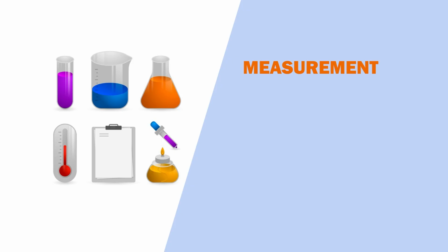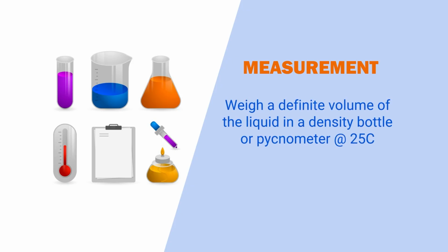So, true density, which is the density of the matter as such, no air entrapment, no air aerated, completely it is only material, that is true density. But if it is aerated, it is bulk density. It is measured first by the pycnometer or by the density bottle. You see it on the right side.